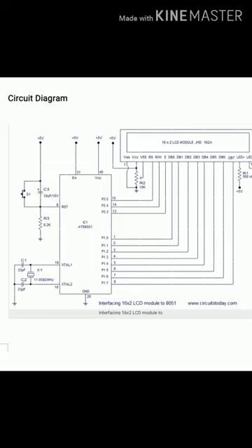Next, P3.3 is the signal which is connected to pin E. Pin E is an enable pin. Therefore, first on P3.3 you will have to send high, immediately you will have to send low, and then generate a delay. That will create a high to low going pulse. So once the high to low going pulse is detected on pin E, the LCD gets activated, enabled. Okay, so this is about the overall interface diagram.